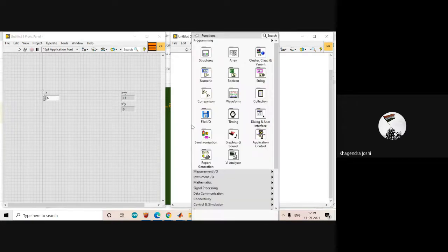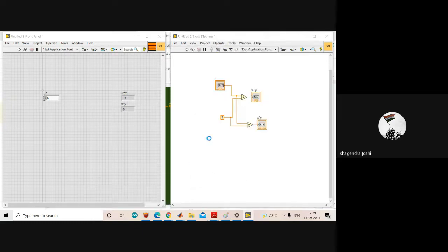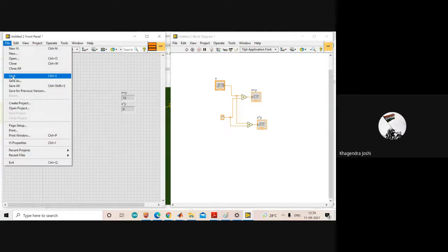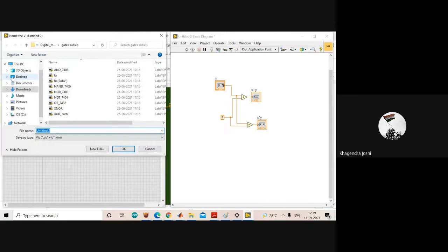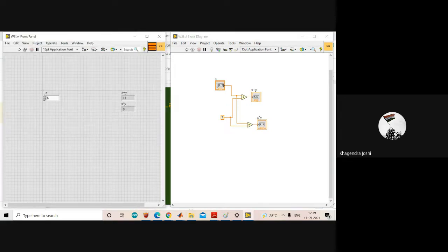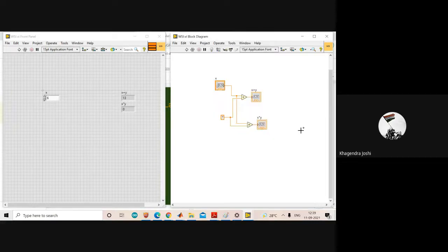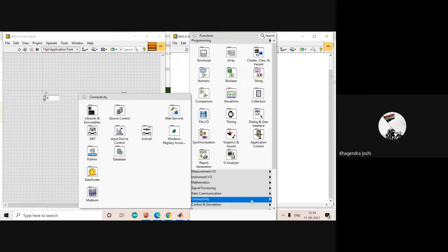So this is, I have matched and I have created a VI. So next time, whenever you want to, there is an option to select a VI. So before that, what I have to do is I have to save this particular VI, right, by the name WSI, suppose. Right? So now I just said that the programmers are working, they are creating sub VIs, and then in the main VI they are utilizing those created sub VIs, right? So how to add a sub VI which I have already created?